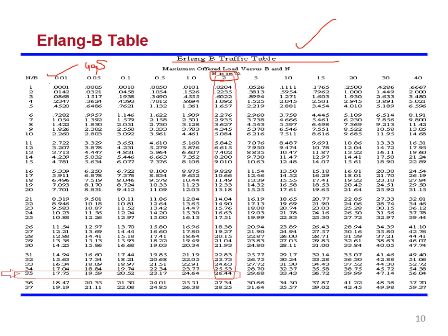Grade of service 2% means nothing but that out of 100 calls made in the network, we can tolerate up to 2 blocked calls due to non-availability of channels, etc. So that is the grade of service. Usually in GSM second generation, BSNL has taken grade of service as 2%.